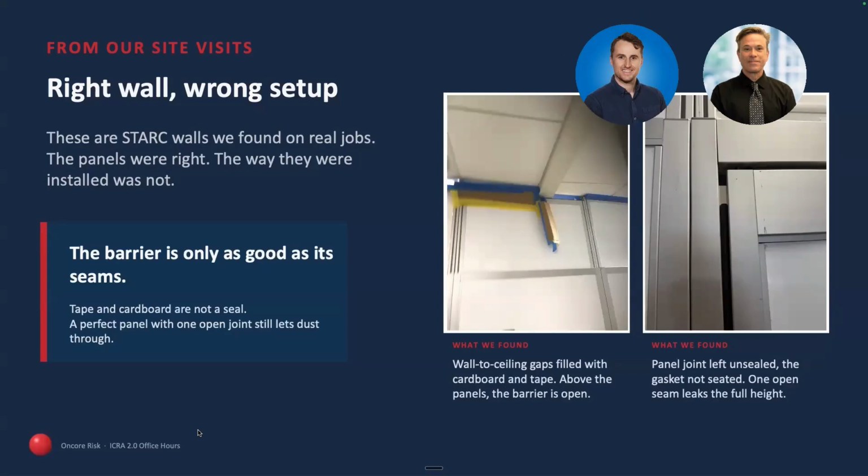You know, as we all know, ceiling conditions are never just straightforward. They're never just flat. And so the way to properly install, in this photo, is we've got a number of widths of panels and then a number of accessories. You want to try to match the height of the ceiling with those various widths and accessories to try and minimize the gaps. And when there is a gap, because of a soffit, etc., because you've got a fixed width panel, you can use the appropriate fire-rated plastic to cut around and seal up that remaining gap.